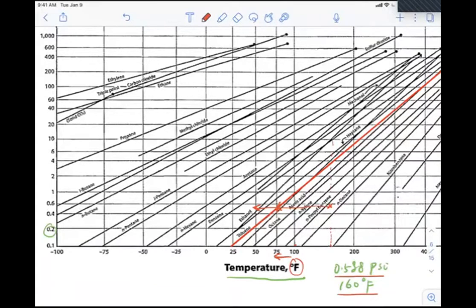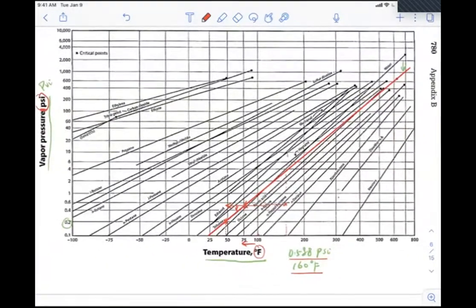The system cannot go across this line, because if it goes across, the partial pressure is higher than the vapor pressure and condensation happens. If condensation happens, the partial pressure is going to decrease, so it's automatically going to change this point back to this line. So we find our final goal, which is to maintain the partial pressure at 1/3 of its original value, which is 0.2. We find this point here, and then you just find the temperature that corresponds to this point. That is the temperature you need to cool down the system. Any questions for this process?